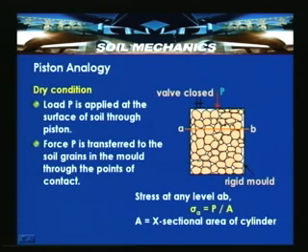So, for elaborating on this relationship, sigma is equal to sigma dash plus pore water pressure, let us consider a piston analogy. Consider a dry condition, assuming that you are having a rigid mold in which the solid grains are filled and a load P is applied over a cross section area A. So, AB is the area which is passing through the voids as well as through the solid grains. And as we have seen, the imaginary area passing through the solid grains as well as the voids is considered in determining the stress at a particular depth within the soil mass.